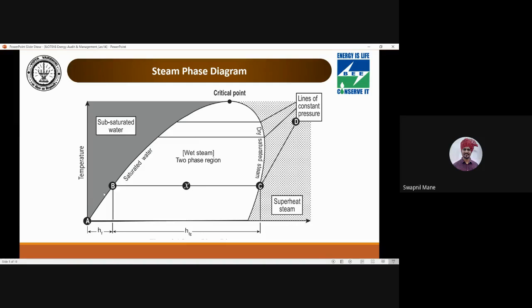As the water-steam mixture increases in dryness, its condition moves from the saturated liquid line to the saturated vapor line. At exactly halfway, if I say this is x, it is neither water nor steam. So 50% is there. We can say x equals 0.5.